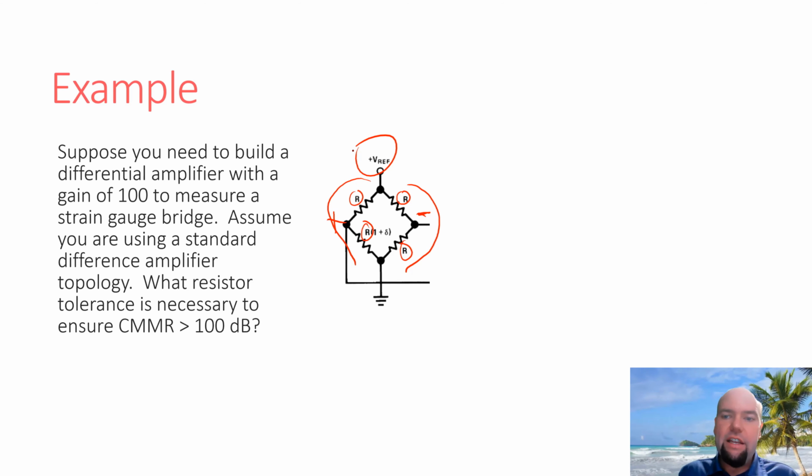The challenge is you're dealing now with a differential signal, so you have to be able to measure it. And it should also be noted that this differential signal is going up and down with the noise from the supply. So the common mode of this differential signal is proportional to the supply noise. So you really want to get rid of that common mode noise. If you don't, you're not getting rid of your supply noise, or not as much. So this is a common need for this sort of technique or technology.